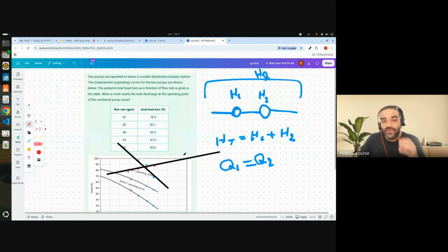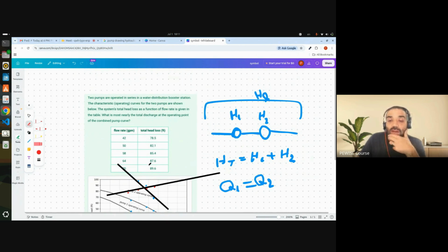To solve this question, you need to have an idea of how pumps in series work. You should remember that the total head added by the pumps is the sum of the heads that each pump adds. Another point to remember is that by increasing the capacity, the head that each pump can add decreases.